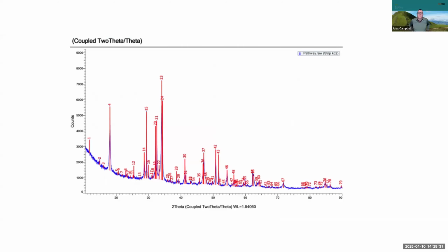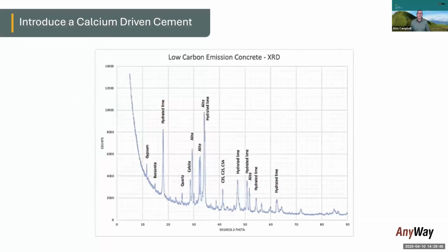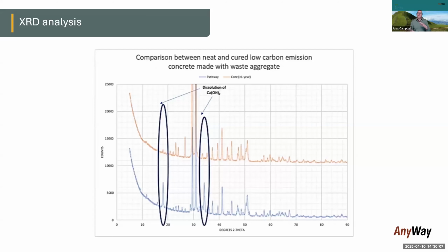We did a lot of chemical analyses using X-ray diffraction. I'm not going to go into what this is, but essentially we're understanding the mineralogy of the materials we're working with, and from that, taking a look at what our mix design or our hydraulic material looks like prior to it being added to the aggregate or the matrix. Then, through a bunch of different tests, understanding what that looks like before hydration and after hydration.